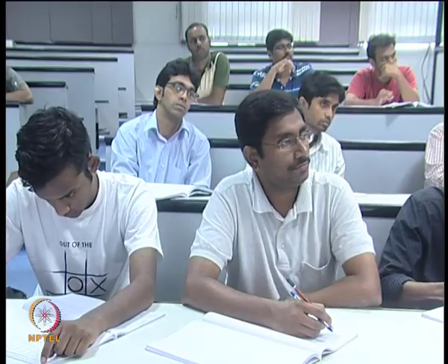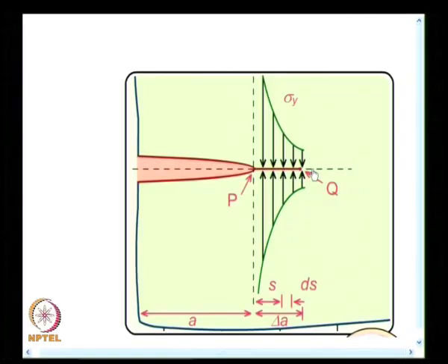Okay. So, in order to visualize that aspect only, the animation was done. Now, for writing Q, you will have to imagine that there was a longer crack like this and find out what is the displacement. Writing P is very simple, this illustration is quite sufficient for you to write what is sigma y variation. Only to recognize the displacement, you have to imagine that there was a longer crack and you should use the value of theta and r appropriately and get the expression.